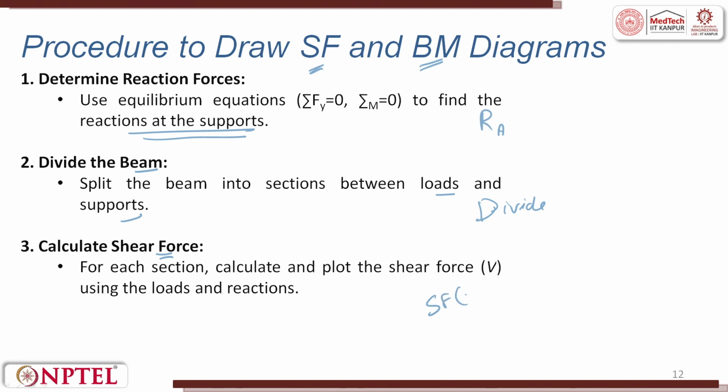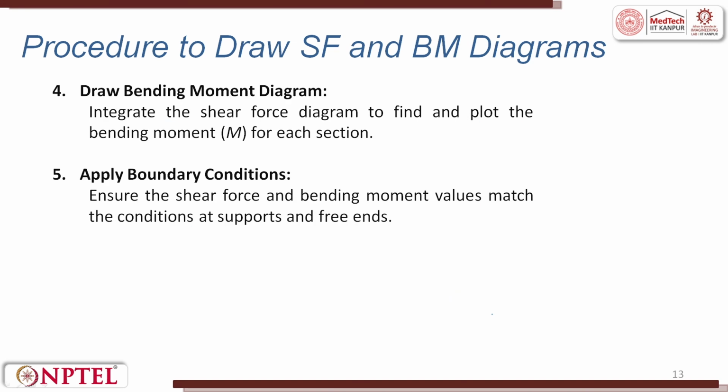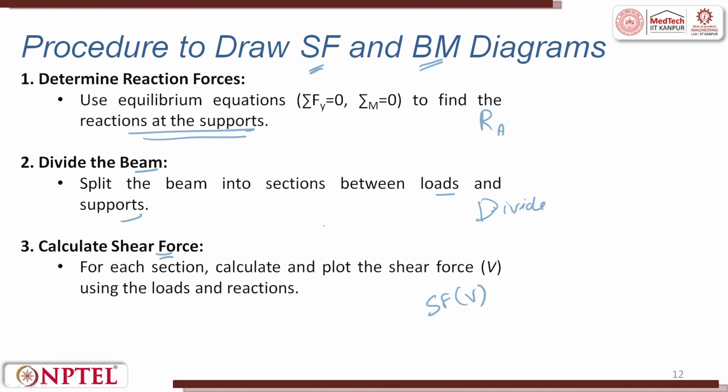Shear force is V. Calculate the shear force using the load and reaction. And after calculating the shear force, you calculate the bending moment. Integrate the shear force diagram to find and plot the bending moment at each cross section. Finally, you apply boundary conditions, ensuring the shear force and bending moment values match the conditions at supports and free ends.